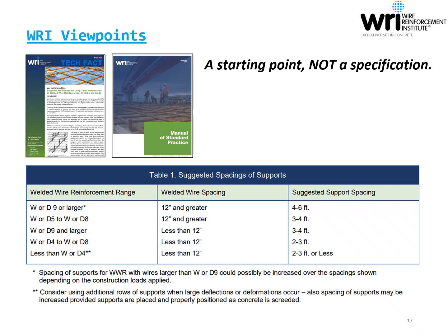First, the specifier must define both the reinforcement's design location as well as the permissible tolerance on that location. Second, the contractor derives and implements a support strategy that achieves conformance within the specified tolerance. The table shown here is a general guide to ranges beyond which the contractor can dial in on their project-specific support needs.